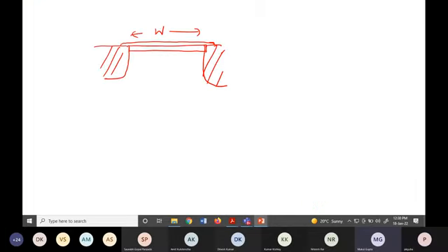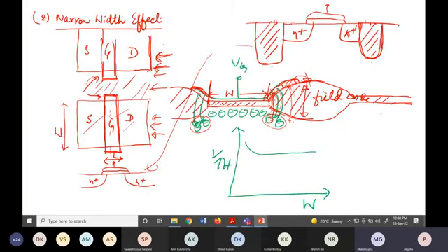So here, even if the polysilicon is here, it will have hardly an effect, because trenches are much thicker. But the way field oxide forms, it is difficult to make it thicker from the edge. It will be thicker eventually, but from the edge it is like a bird's beak, right? So it will not be thicker. That is why this fringing effect will be there, right?